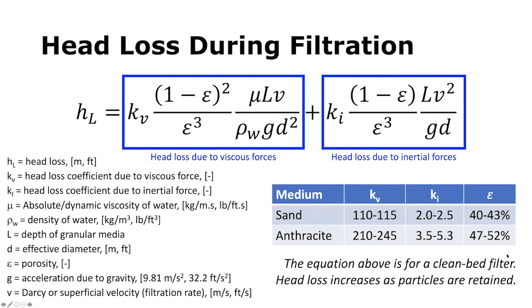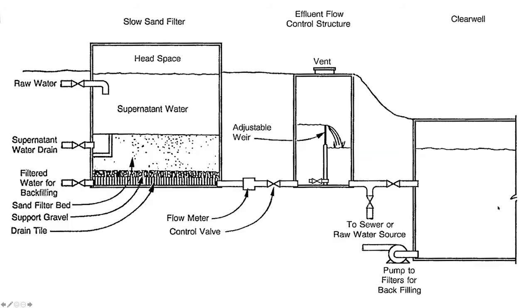And so this equation is for a clean bed filter. However, it should be noted that head loss increases as more and more particles are retained on the filter. When it increases to a level that's too high, of course, we would need to initiate backwashing.